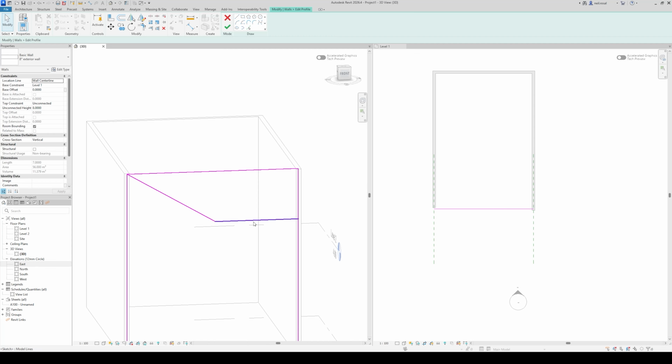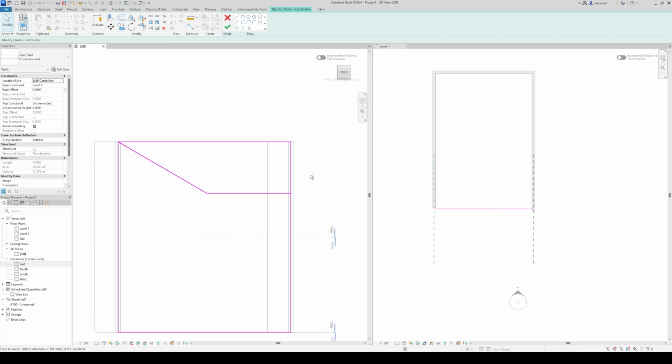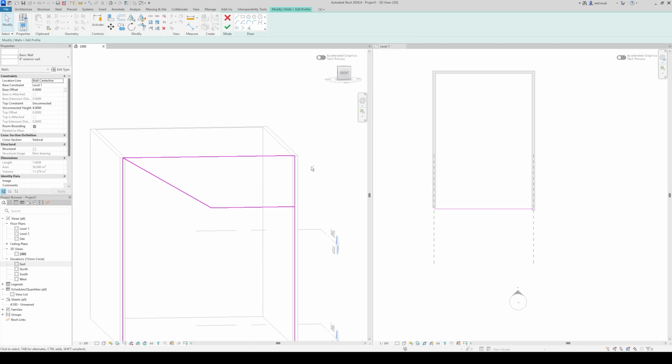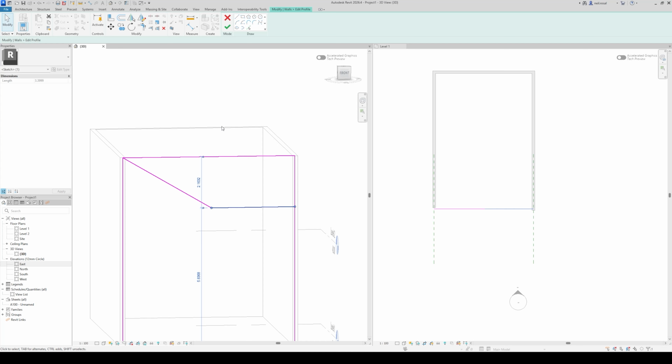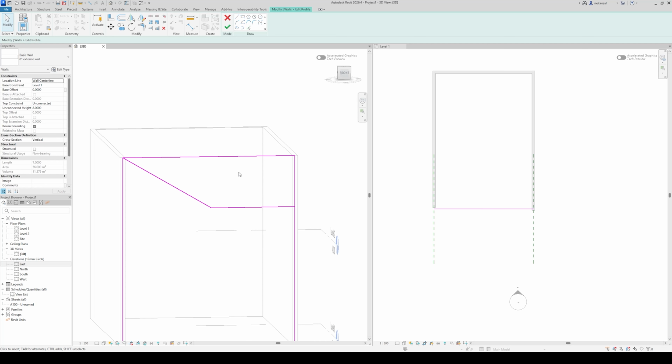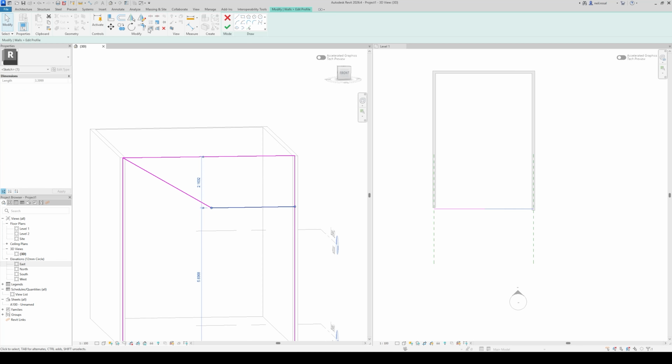With Revit, you can trim your elements like walls and your floorboards, and that's how you can get that profile. Trimming in Revit is kind of the opposite of Rhino. So they're over here in the modify tools section. I want to select this specific trim/extend single element tool. There's different types of trims.